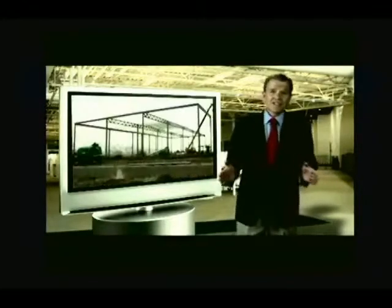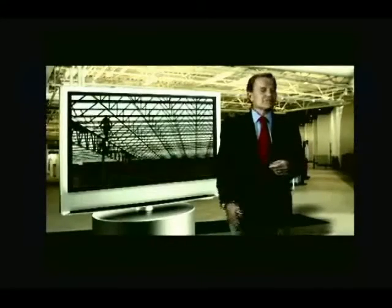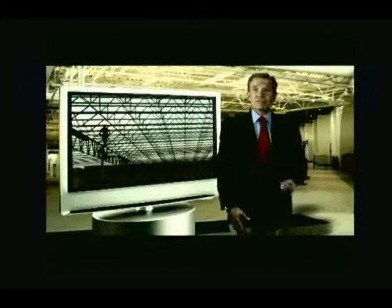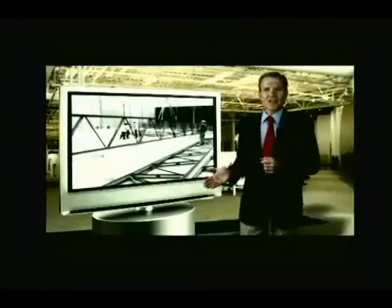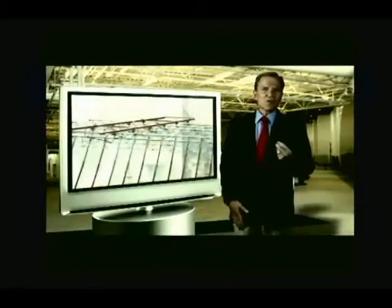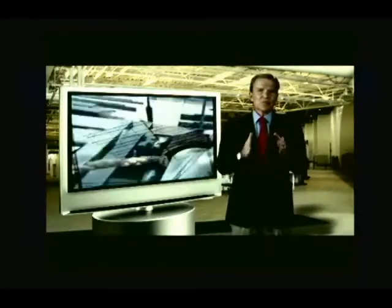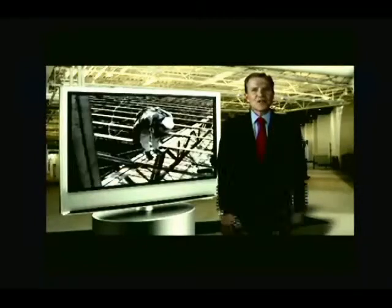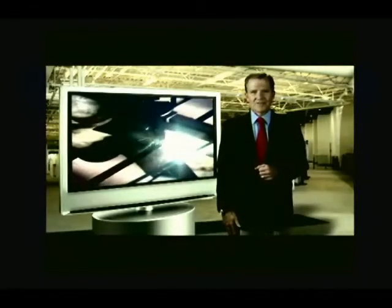Flexibility is another advantage. Unlike any other building products, steel joist products are standardized in a wide selection of depths ranging from 8 to 120 inches and spans from 8 to 144 feet with varying loading conditions. With their unitized construction, they eliminate the need for job site assembly, preparations, forming, stripping, or the like. They provide an immediately available working platform as soon as the joists are properly erected, bridged, and welded in place, and the metal deck attached.